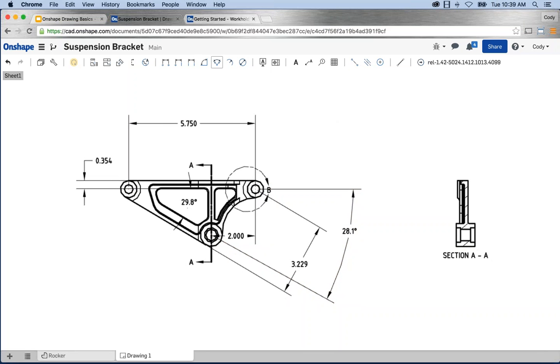Okay, so I've covered the 2 different angular dimension types. The last 2 we have are very straightforward. We have radial dimensions and, of course, diameter dimensions. And like the name implies, it really just depends what you're trying to dimension. So if I just want a dimension of a radius, I select radial dimension, I select the arc, and it applies a radius value to it. So very straightforward. As I mentioned before, you can also edit dimensions. So a very common thing, for example, is to edit a dimension and add some text here. So I can add 4x, for example, or it shouldn't be 4. It should be 3x. Right? So I can define 3 of these. So you can go through and edit each of these dimensions as you choose to with that dimension properties. But radial dimensions, very simple.